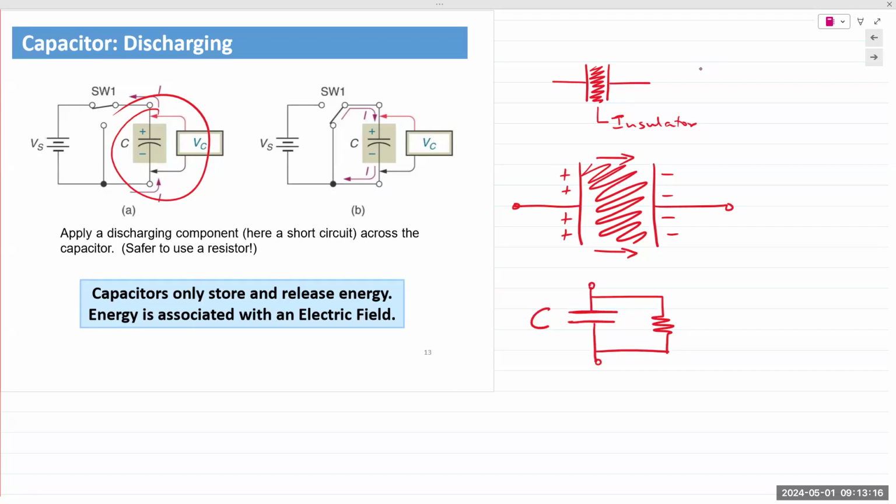Of course, that resistance has a very, very high value. So it behaves like an insulator in most scenarios. But if you take a fully charged capacitor out of its circuit, after a certain period of time, that capacitor will lose all of its stored energy. And we can say that it loses it through that parallel resistor. So for an inductor, we model the resistance in series. For a capacitor, we model it in parallel.